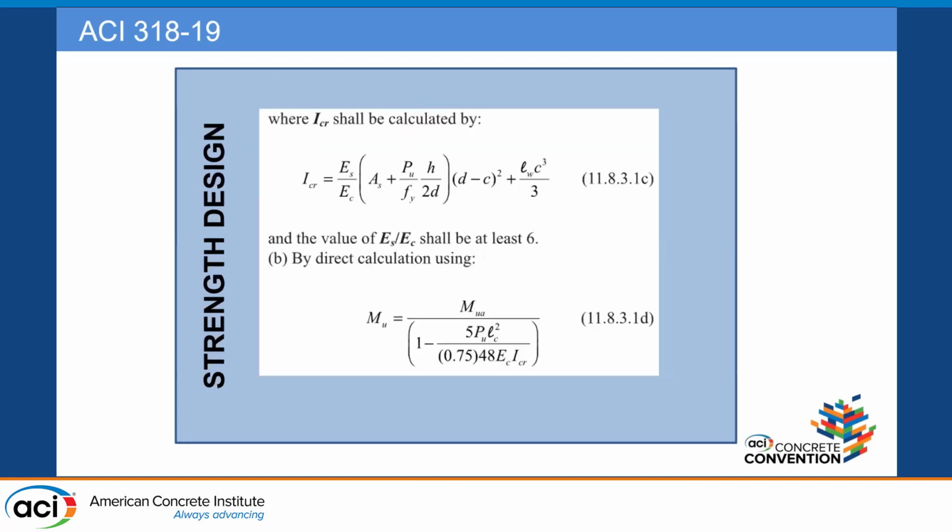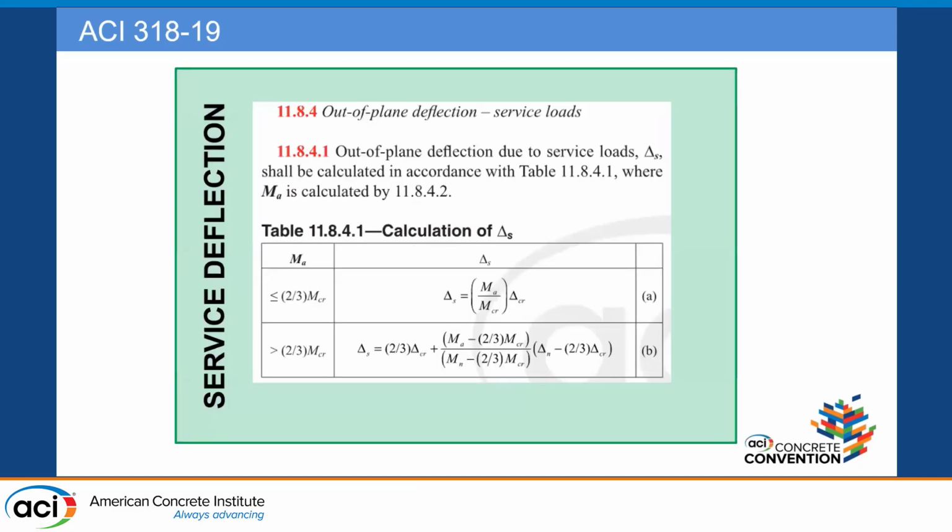So the second part of this though, comes down and it gives you by direct calculation, and you can use this equation to do this. And I'll show you in a minute, these should be exactly the same, okay? Regardless of what you use, as long as you use a cracked moment of inertia for your calculation. And that cracked moment of inertia is right up here, and here is the equation for it that they're asked to use.